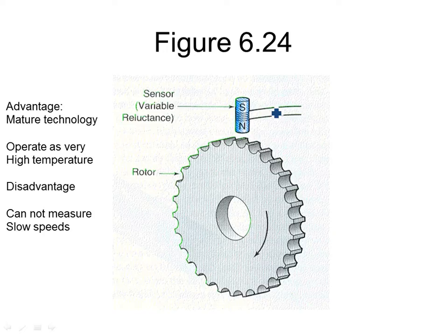So what happens is when this gear is spinning, every time it spins past one of these chunks of metal, what does it do? Puts out a little pulse, and then we run that into electronic circuits. So what do you see now? You see your speedometer. If you take it apart, all you're going to see is electrical wires coming to the back of that thing, because they use this variable reluctance pickup. And where's it at? It's inside the transmission.